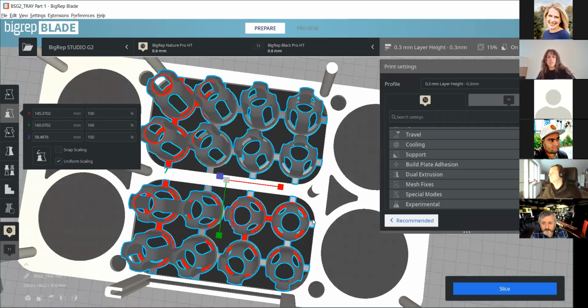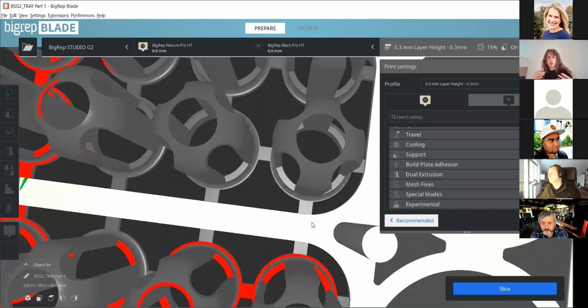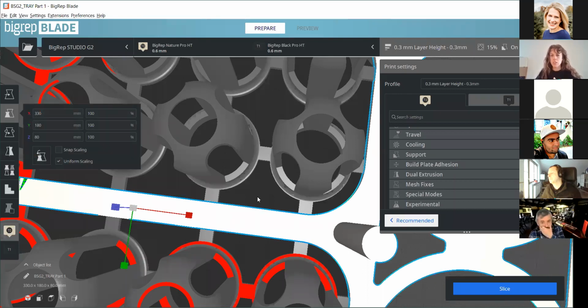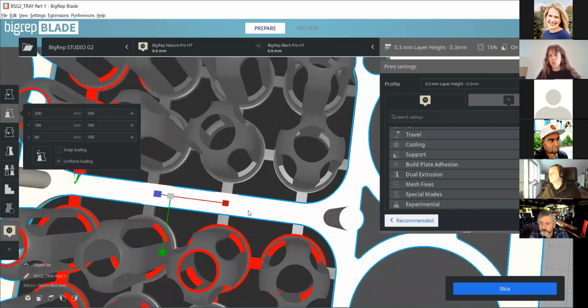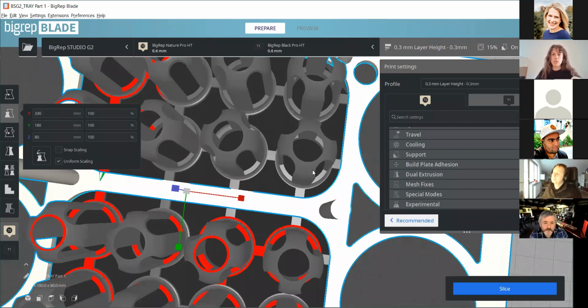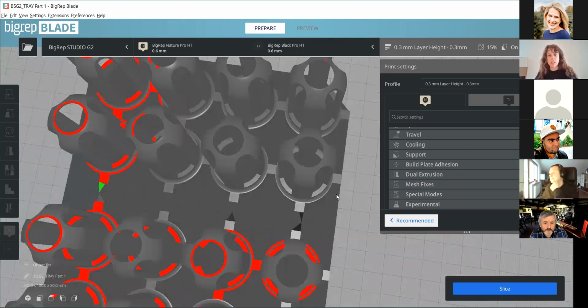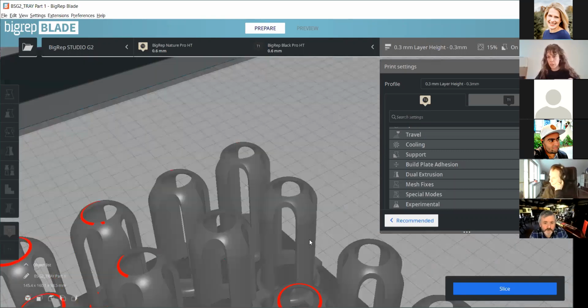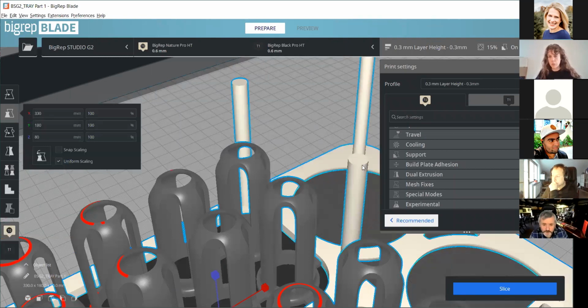I mean, there's technically the only separation essentially when I'm in Rhino and I've modeled this, because this actually was one part to begin with. So I brought it into Rhino and I essentially selected all the meshes that were in the bottom tray and put them on one layer. And then I selected all these and put them in another, so that essentially I could hide that. And this would print on its own fine. So even if I didn't bring that other part in, this is an enclosed solid mesh file. And this is also an enclosed solid mesh file.